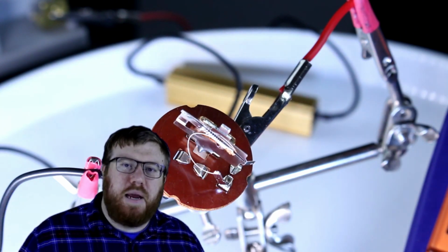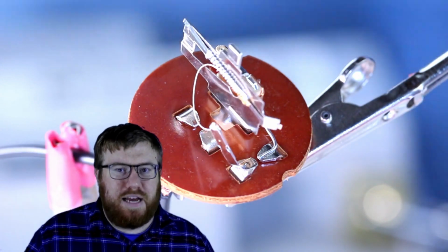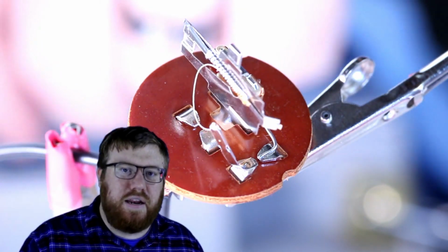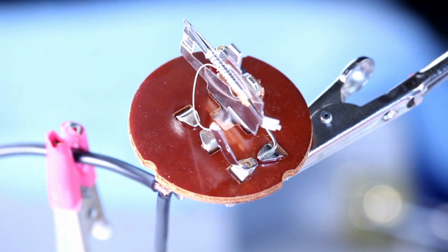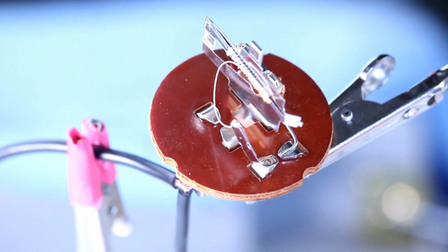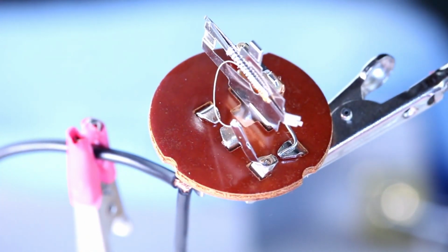That strip of metal is made out of a different material than the metal it's attached to, and it will expand when heated at a different rate. Because both of these pieces of metal are attached at two points, when one expands, it's going to want to bend the other. Eventually that strip expands to the point where the secondary piece of metal gets pushed into another electrical contact and allows electricity to flow through that instead of that wire.